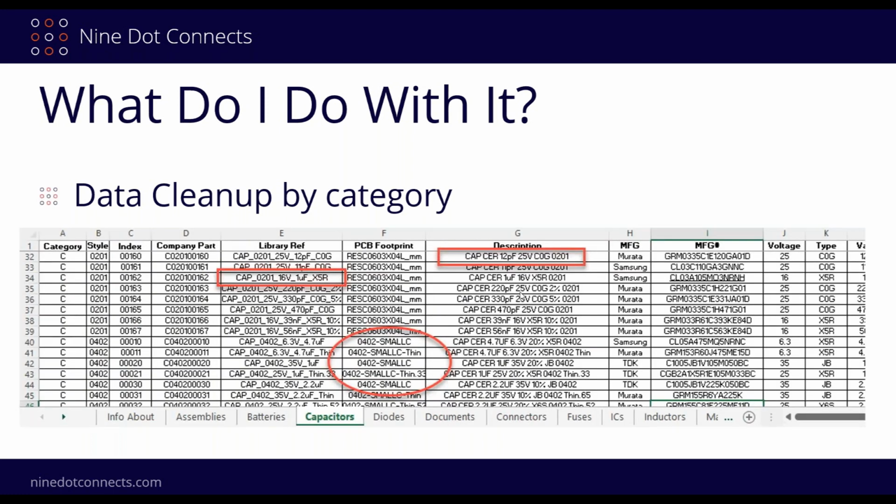And so here's an example of it right here. This is a really good example of a description that you can read. What did it say? Well, the prefix here is cap. So you know it's a capacitor, what type of capacitor in terms of its material, the value of it, the voltage rating of it. Well, this is ceramic, but this is also, I think, another material aspect of it. And then, of course, the footprint of it as well. And if they even had a percentage, like its tolerance. So it's very consistent, which makes it easy for sorting and to look at as well.